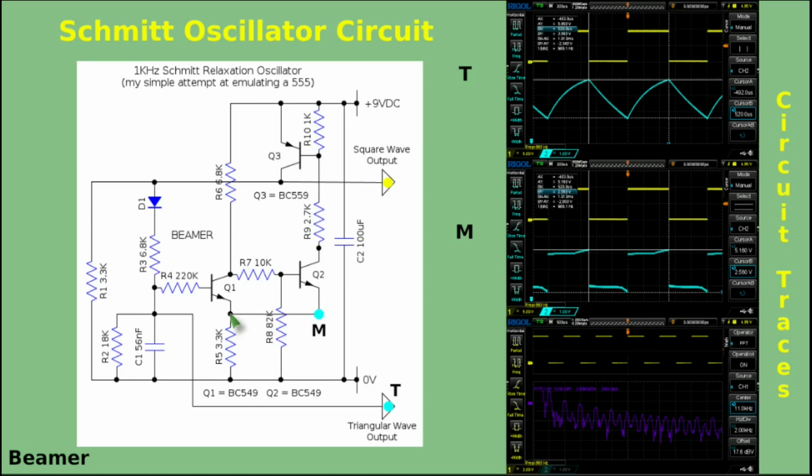And that is essential for a Schmitt trigger, because the hysteresis that we spoke about going on the base of Q1, the threshold is being shifted by the two states of current arms that are feeding into R5. So all the while you've got 1.5 milliamps flowing through here, the threshold is high. But when it switches over to here, the current flowing through R5 is 0.85 of a milliamp, and that ensures that the threshold, the trigger point, is dropped nearer to 0.